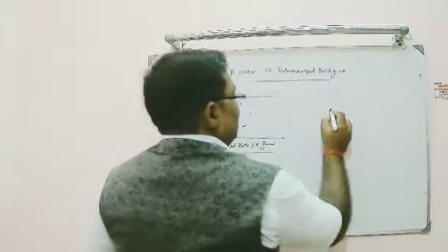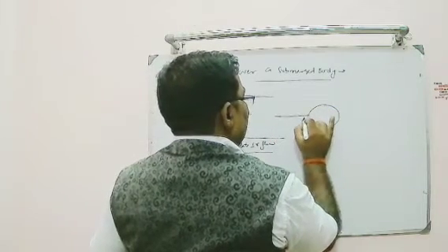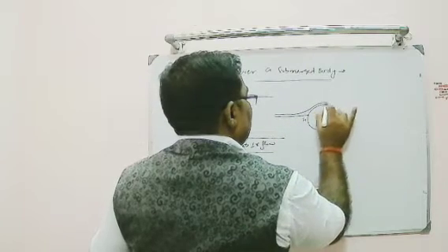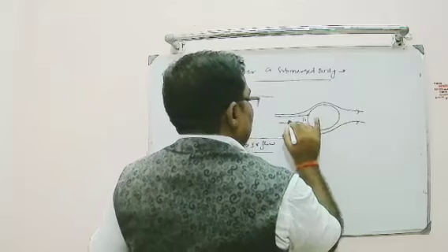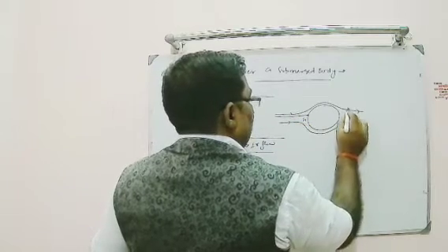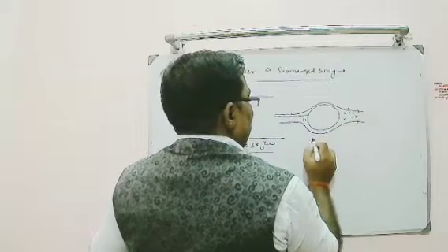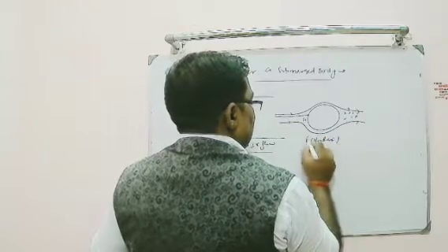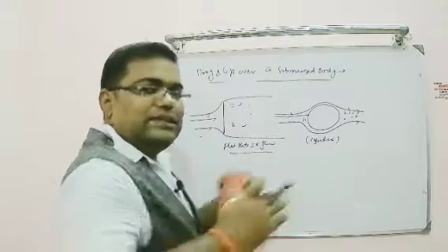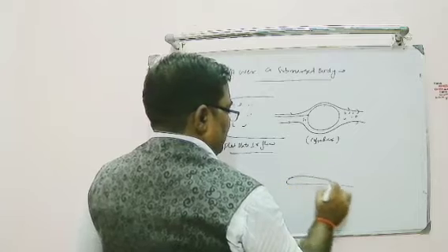The second case is a circular cylinder, with flow coming like that. The first stagnation point you will get here. Now the flow will go like this and travel up to here, and go like that and travel up to here. If you look here, some wake formation will take place. So this is the cylinder case. Now consider a more streamlined body, the airfoil.